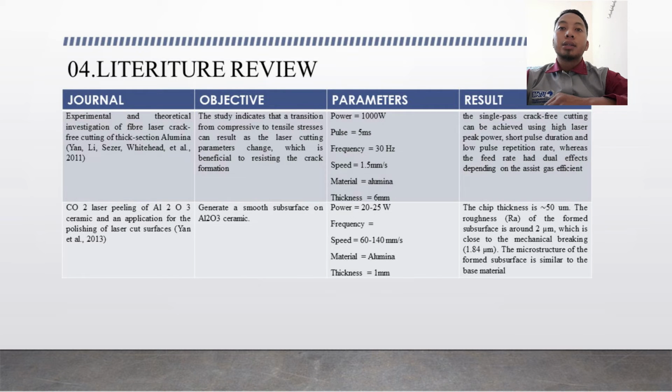The result is that the chip thickness is around 500 micrometer. The roughness of the formed subsurface is around 2 micrometer, which is close to the mechanical grinding value of 1.84 micrometer. The microstructure of the formed subsurface is similar to the base material.